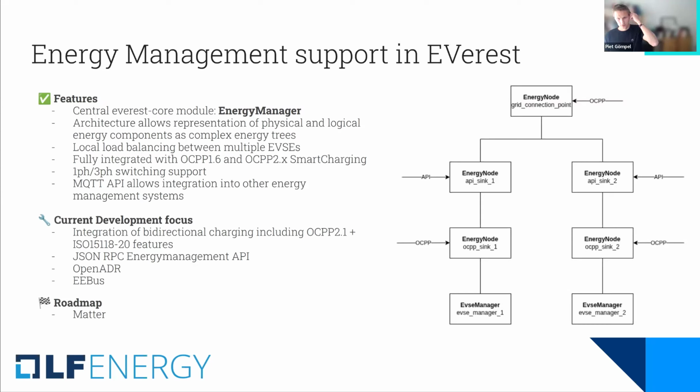We are currently focusing on the integration of the bidirectional charging. It has support for it already, but as probably many of you know, OCPP 2.1 and also ISO 15118-20 come with a lot of additional requirements with respect to the energy management and discharging of EVs.